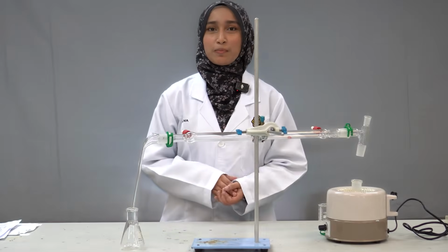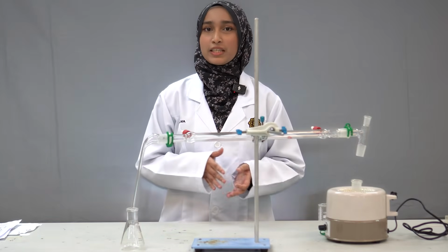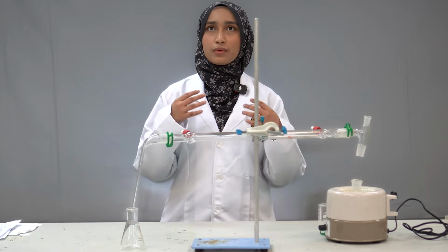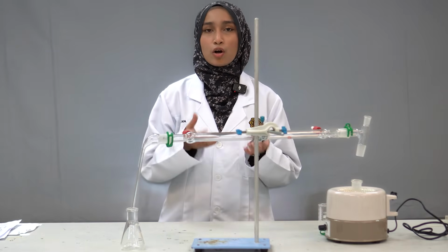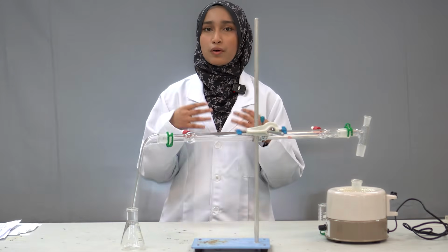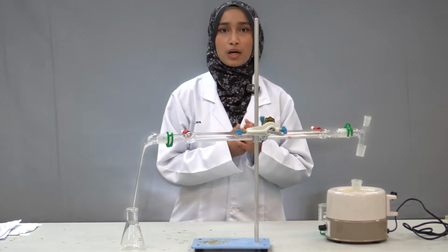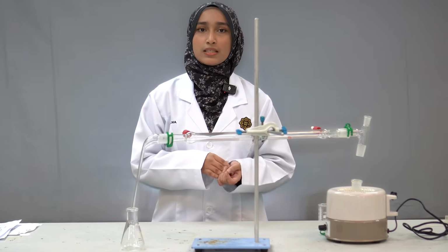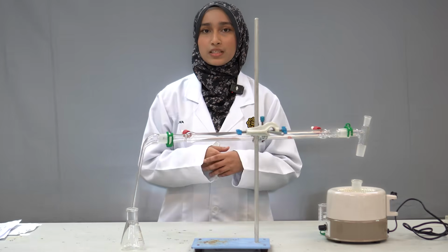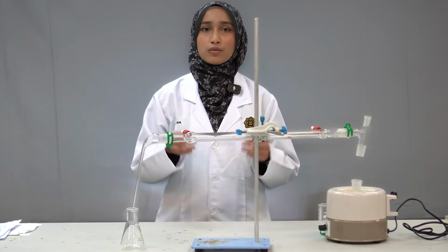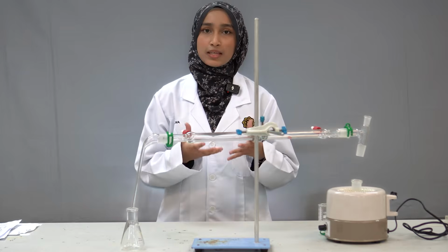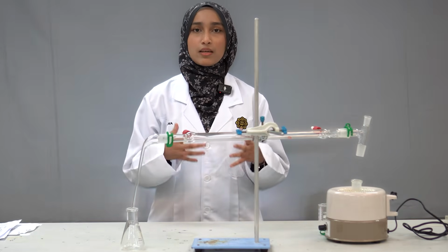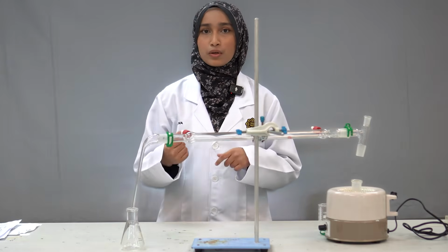Alright, so next I will explain the industrial application of the distillation principle. So in industry, it involves a more complex distillation process with the use of larger equipment to produce a larger outcome of distillation product. The most prominent industrial application is petroleum refining, which is the fractional distillation of crude oil. Crude oil is a complex mixture of hydrocarbons with varying boiling points and densities, and it is a natural liquid fossil fuel found underground.